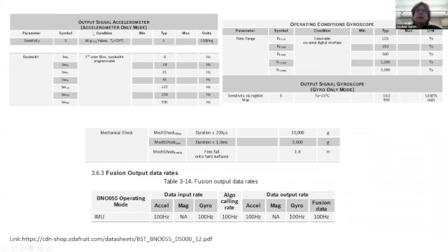The bandwidth of your accelerometer is more important for transient acceleration measurements, so measuring vibration. You can set the range rate of degrees per second that your gyroscope is going to be measuring angular velocity in.